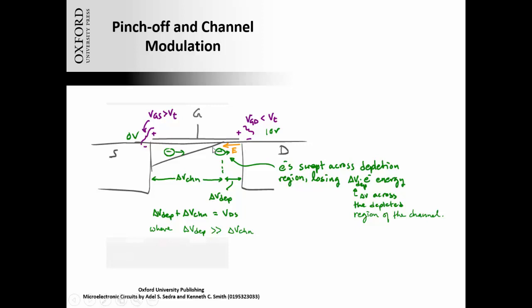Well, that's going to be essentially the same case here. The net voltage between the left side, where the channel meets the source and is at 0 potential, and over here where it gets pinched off, which is basically 1 volt from the source, that electric field is going to be pretty constant. It will only change if this channel length changes, right? Why would this channel length change?